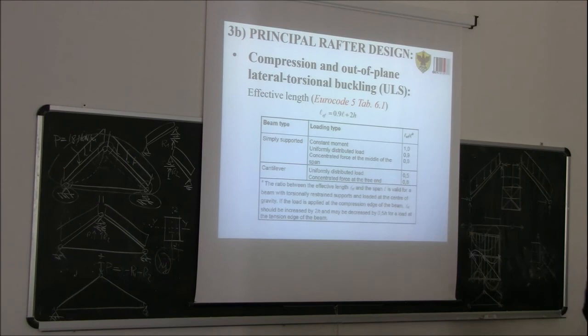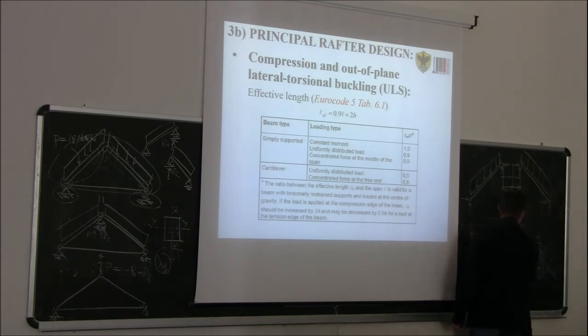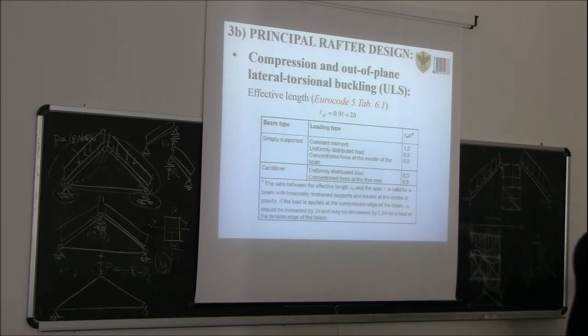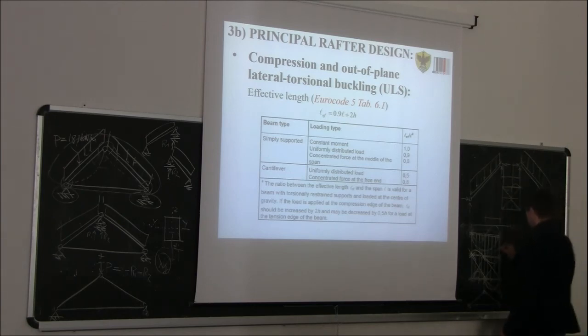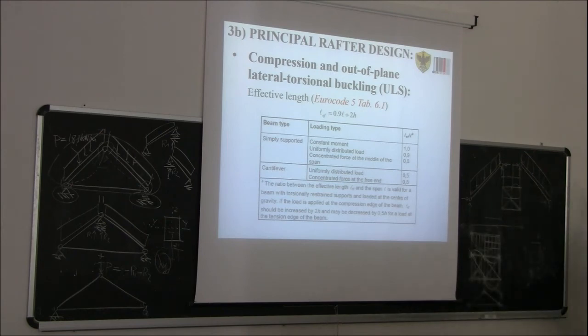So, on top of the pyramids, rather than having small boards, which makes this roofing unstable, use big panels. So sheets or sheathing of wood, 1.2 meter times 2.4 meter, nailed all around the perimeter. So replace the small and narrow boards with two-dimensional panels.